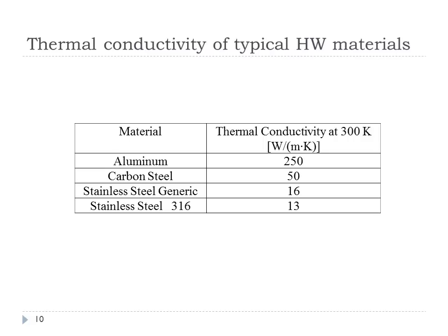If you need steels that can handle fluids that might be caustic, like sodium hydroxide in aqueous solutions, you're likely going to need stainless steels or stainless steel 316, and you can see here that their thermal conductivities decrease. That is somewhat unfortunate, because as you make the steel more tolerant to impurities and to caustic materials, its heat transfer coefficient drops. Also, compared to carbon steel, stainless steels are more expensive.